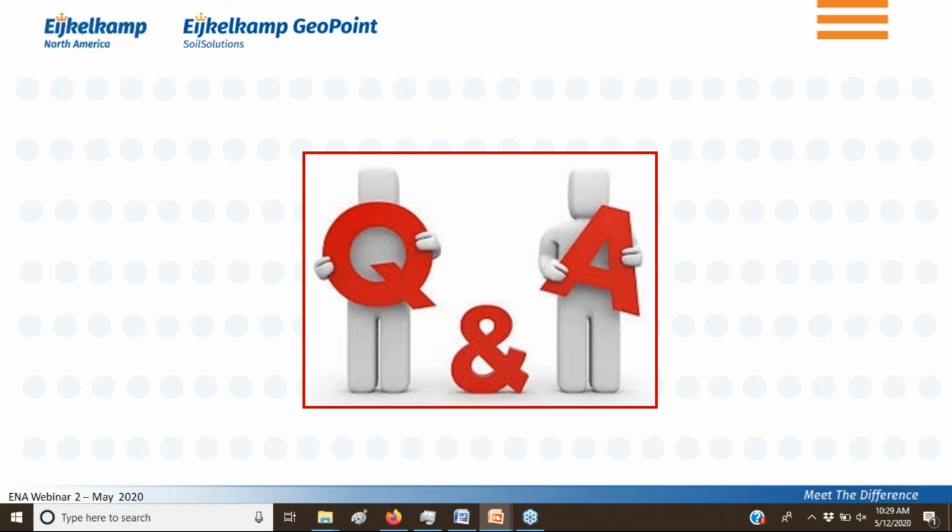If you have a blow count of 100, and you have a 20-ton truck, you can still, with a 15 centimeter square cone, push that cone through there. Which means that softer rocks, you can go through there. Stiff sands, you can go through there. Even gravelly sands, you can go through there.